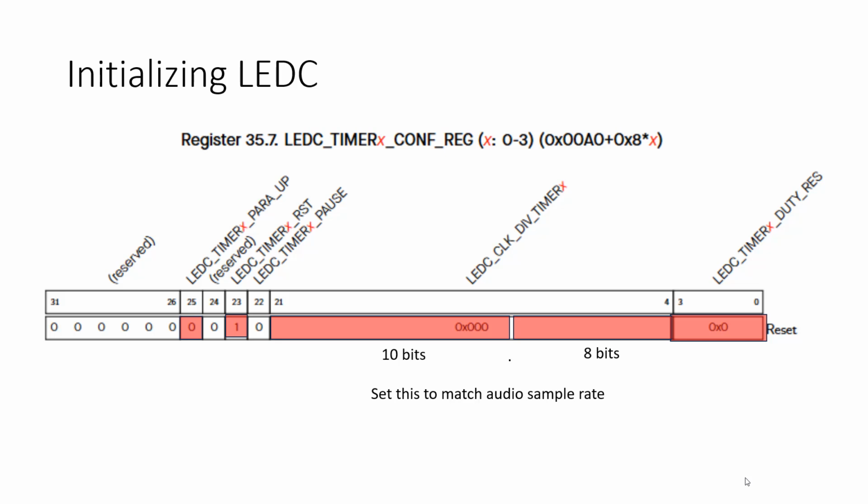Please just compute it in your code. It's way easier that way. See, now when I wrote this originally, I didn't see any need to have one PWM period matched directly to one audio sample period because I figured, well, the PWM signal could oversample, right? Like I could send 10 PWM periods for every one of the actual audio samples stored in the file. So that's how I did it.